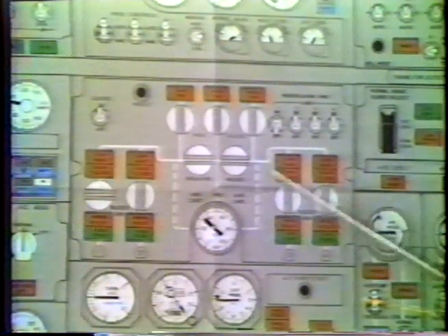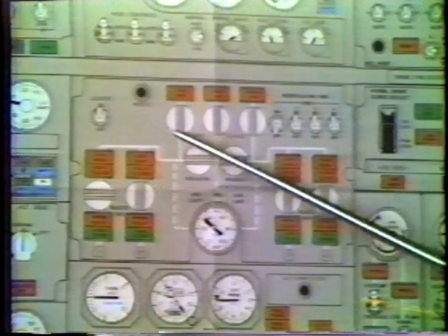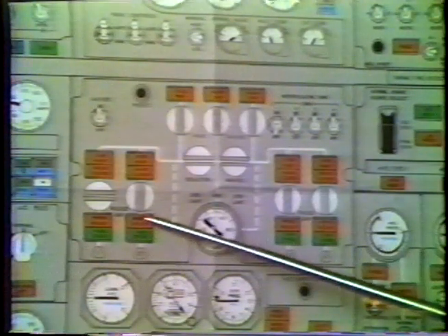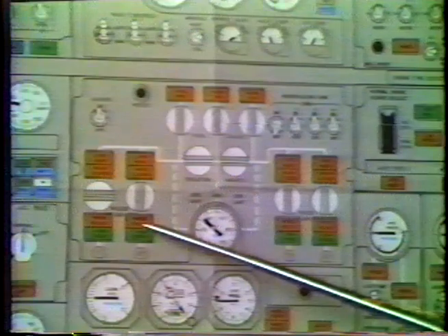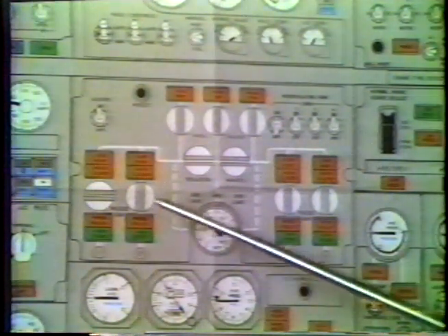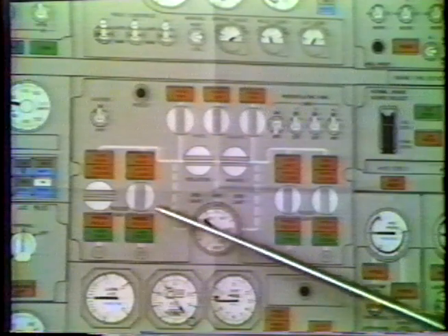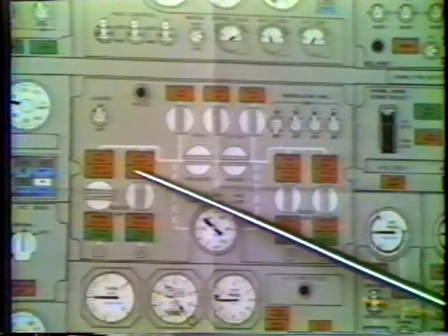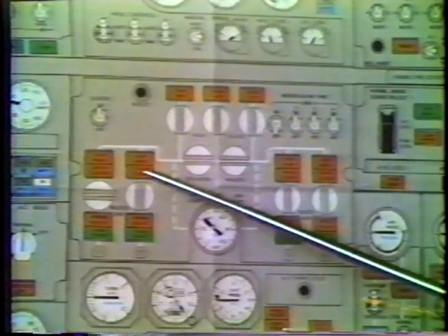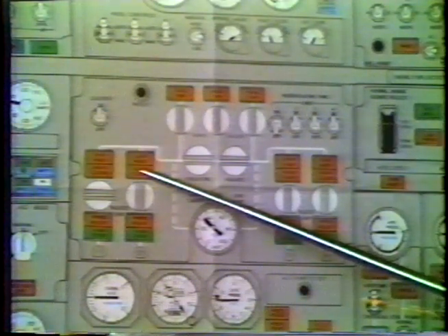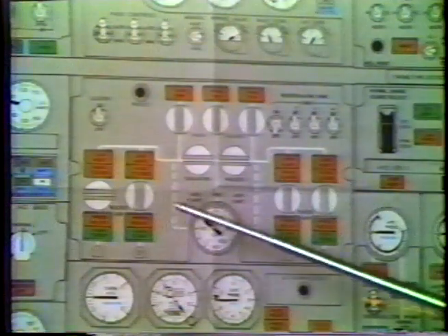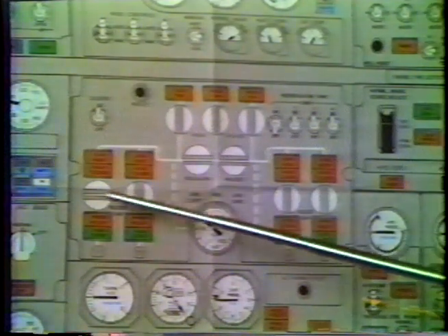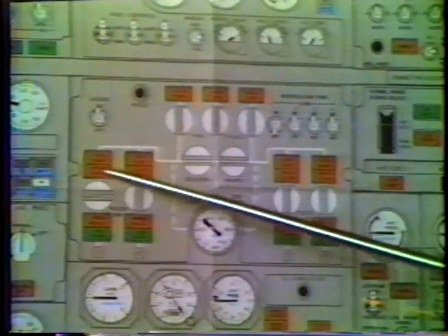Now, normally, when you go to start the engine, pneumatic air has to come backwards through this valve, down through the pylon to the starter on the engine. And through the start switch on the overhead panel, it will bypass the check function of this valve. So the light goes out when you operate the starter. In addition, a valve on the starter will operate, and a green light on the overhead panel will indicate the starter valve is open. If this switch is left in a closed position, the engine cannot be started.